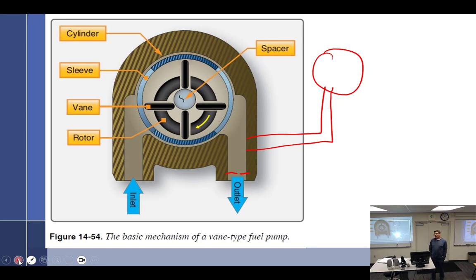And starting an engine with a fuel injection system or pressure carburetor is very different than starting with a carburetor. So with the carburetor, like with our test stand, you can turn on the fuel pump, because we use a fuel pump on our test stand. And because the tank is low, the fuel pump pumps it out.